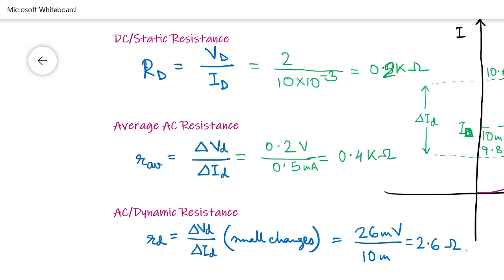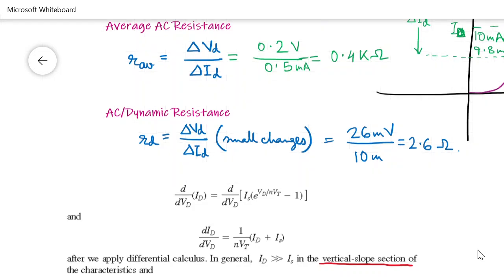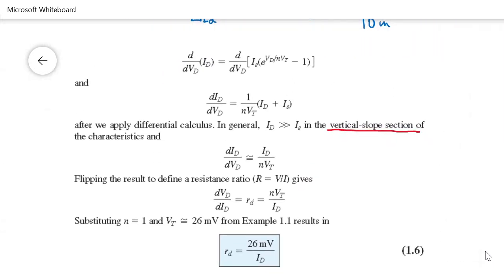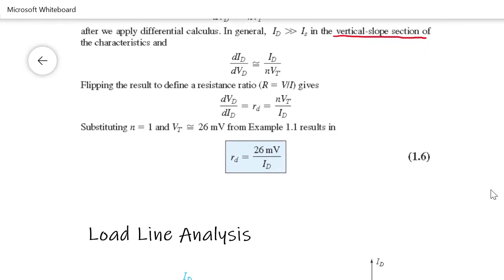So whatever you measure during reverse bias is the reverse saturation current, and that will remain constant throughout the reverse bias region. It is specific to the particular diode and comes from the diode data sheet. The manufacturer will give you the reverse saturation current, and you can verify it by putting the diode in reverse bias and measuring that current.